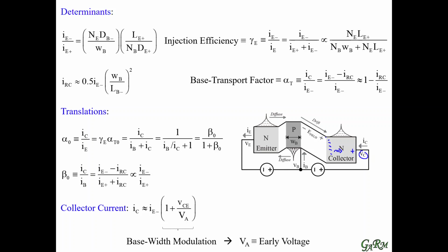That means that the depletion region is going to expand. Putting a positive voltage at the collector with respect to the base is like putting a negative voltage at the base. And a negative voltage then will pull holes at the edge of the depletion region back. So what we get here is that the depletion region expands with a positive voltage.